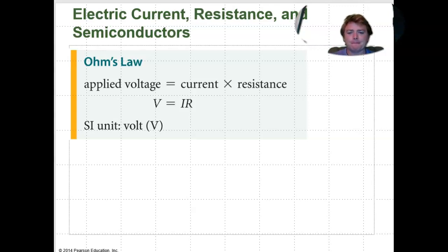Now for Ohm's law, we have the voltage across is equal to current times resistance, and then of course we can rearrange this a number of ways. Voltage is the product of current and resistance. We typically ignore the resistance that is within a wire, but when we look at a resistor, we can determine either the current that's going to be across it based off of the voltage across it, or the voltage based off of the current. And for a single resistor, that's pretty easy for us to do. We have an EMF, we have a resistor, and they're connected.